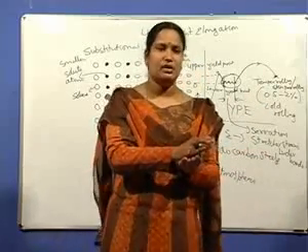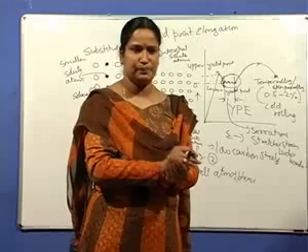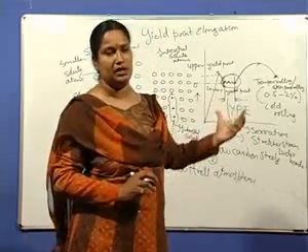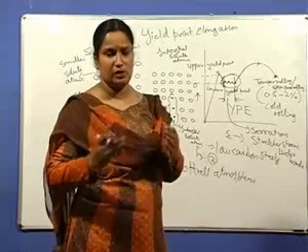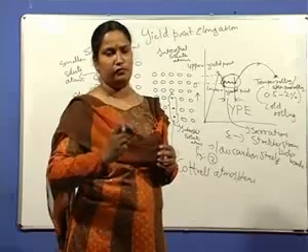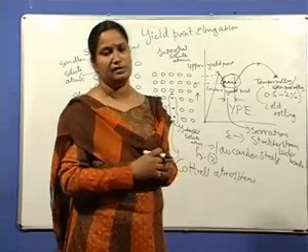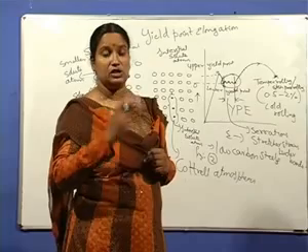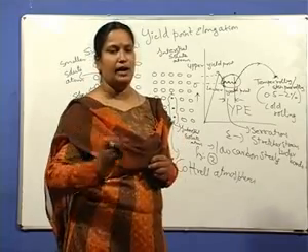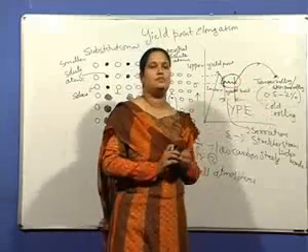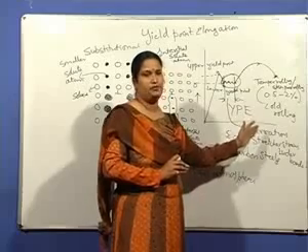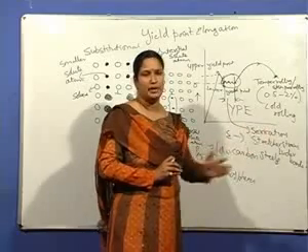The main aim is to give a small cold reduction, thereby avoiding this yield point elongation, so that more dislocations are generated and they can easily move, crossing these barriers, and be torn away from the solute atoms, and the normal stress strain curve is observed, because they form an objectionable surface during sheet forming processes.